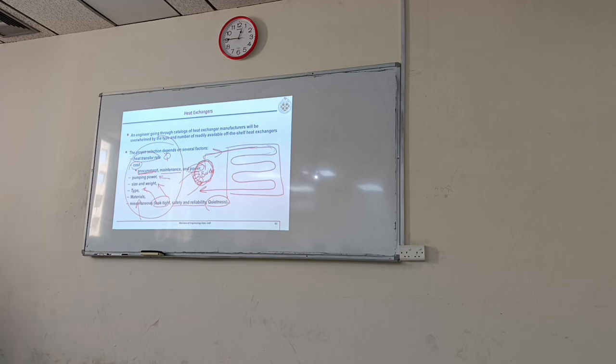This room air should come in contact. And also there is radiation heat exchange. The radiator is at low temperature, we are at high temperature. So there is radiation heat exchange plus there is convection. Okay, so you will eliminate this noise, but both have their own advantages and disadvantages. But here you should have a separate complete wall or complete roof. More expensive. It's difficult to say expensive because this is being used in large buildings, radiative cooling. Yeah, the whole roof is filled with these pipes when they are making.